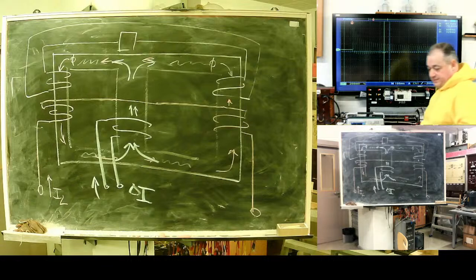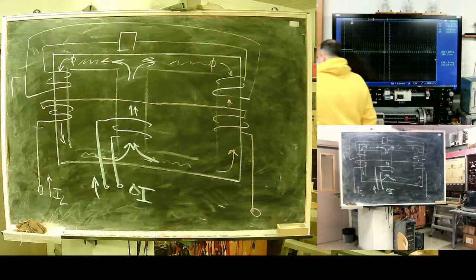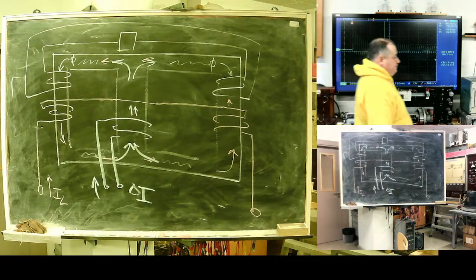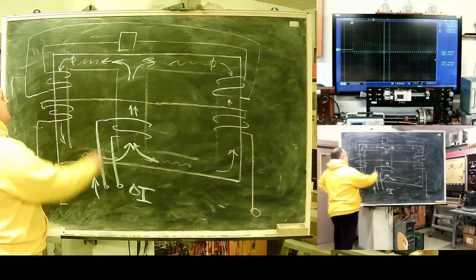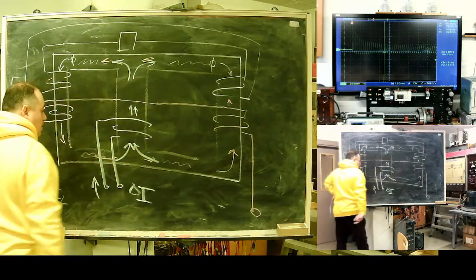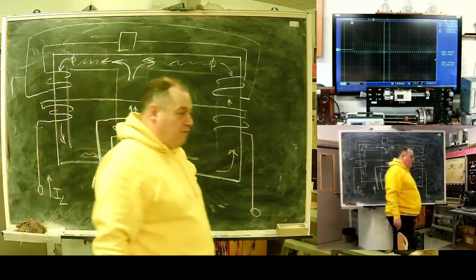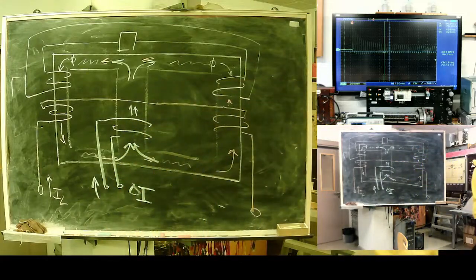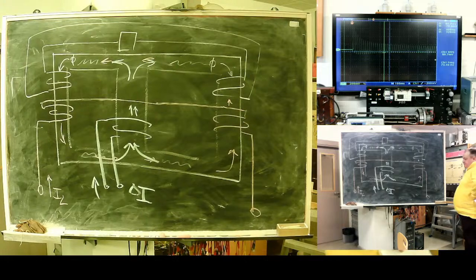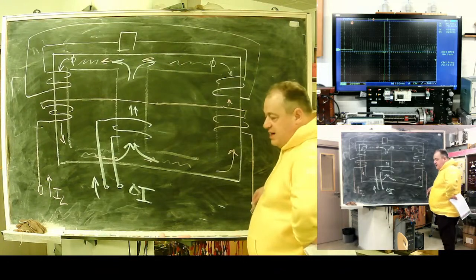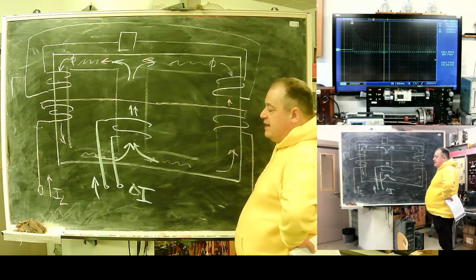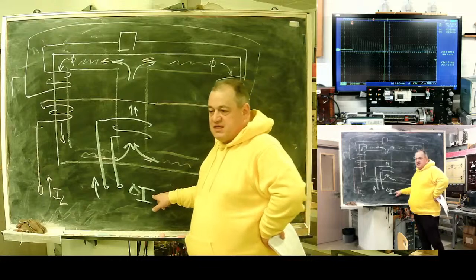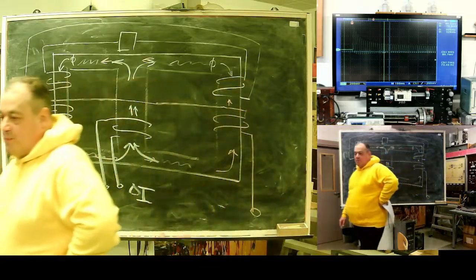The blue one works to operate, but the red one saturates areas where the number of sheets in the core is halved. The higher the red one, the higher the necessary difference in currents for the relay to operate.